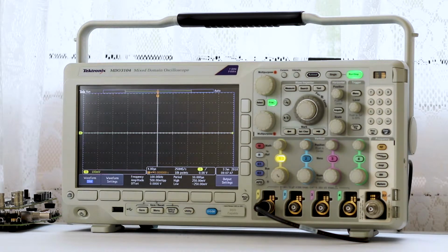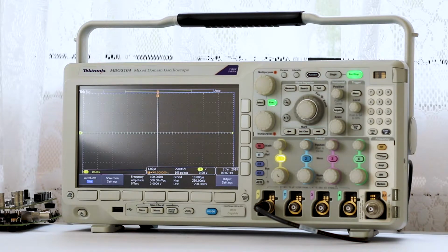In the DSO, the signal passes through the input channel where it is amplified and/or attenuated, then scaled and digitized in the analog to digital converter, ADC, one for each channel. The instrument samples this data stream and, governed by user-selected protocols, extracts the samples and creates waveform records, which are placed in the acquisition memory.